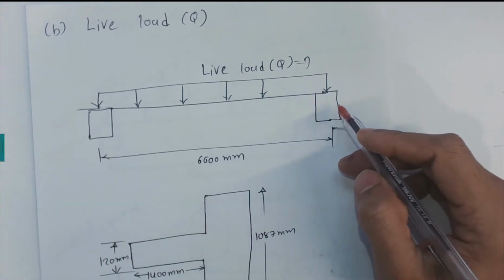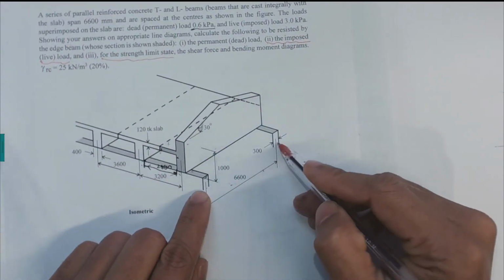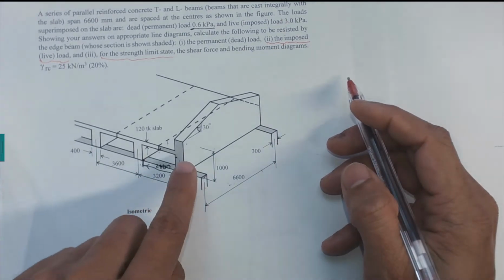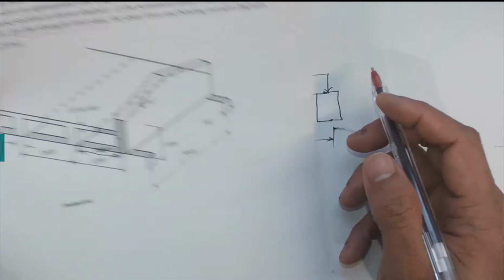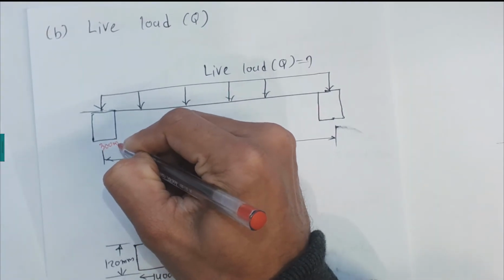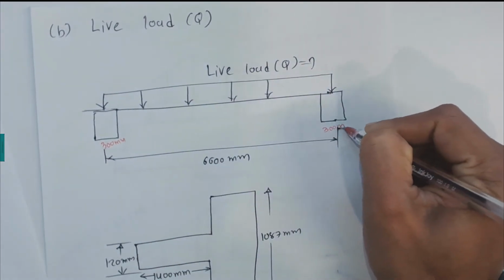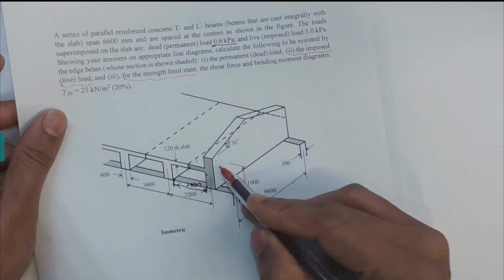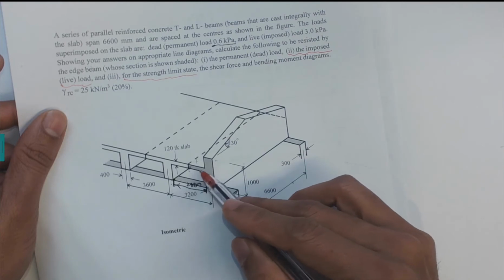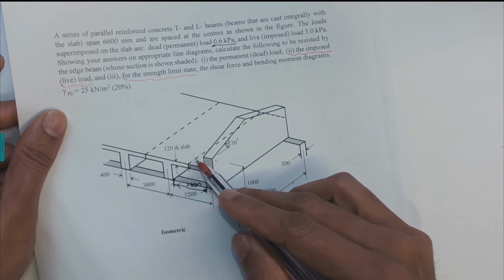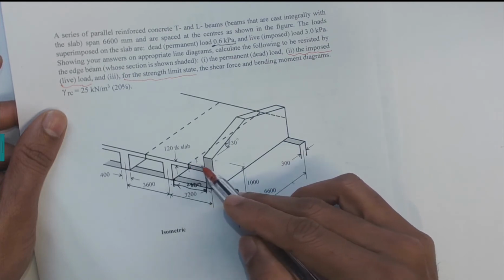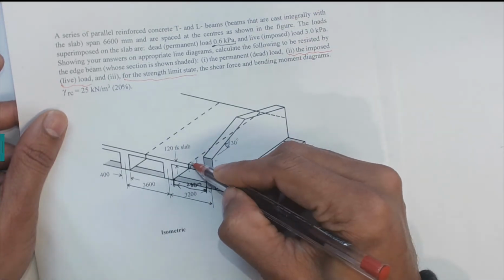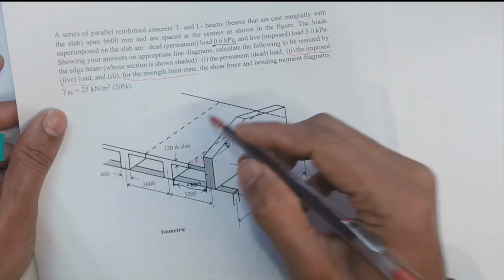As we know, we have an H beam. If I can show that H beam here, those are the H beams which I draw here, and each beam is 300 millimeters wide. So these are 300 millimeters and 300 millimeters, and on the H beam this line is a slab, and this slab has this flat portion. Now for the case of live load where we don't have a dead load, the live load is going to be applied only on this portion, which is 1400 millimeters, which we calculated. So the live load could be only on these portions for this particular beam.